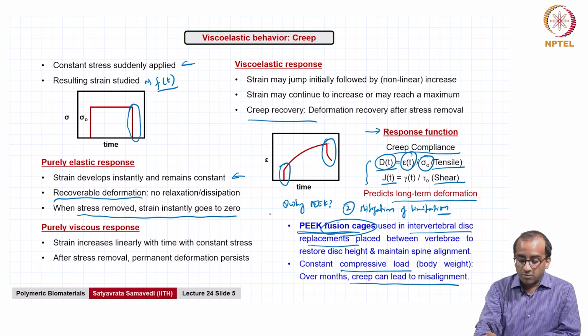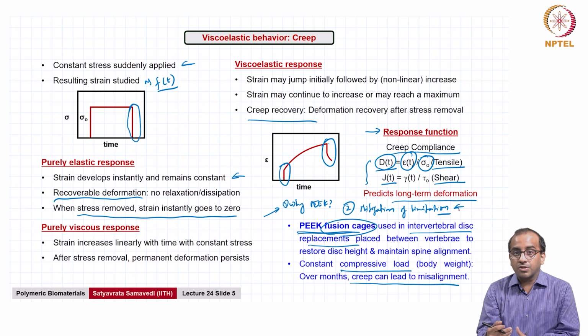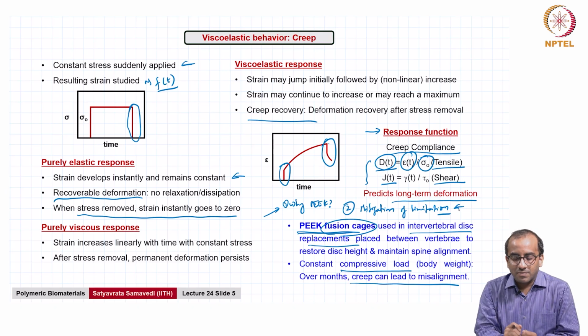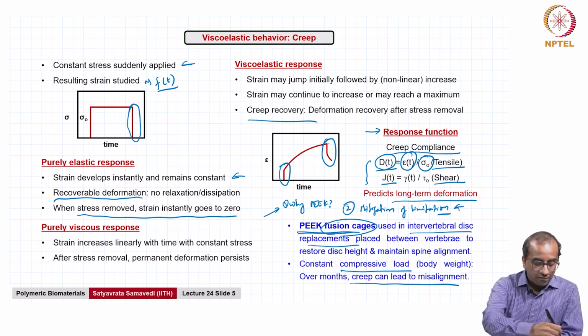The first one is more of a scientific question. The second one is more of an engineering question, because here you are asking from a design perspective, what do I need to do to ensure that creep isn't significant once I have implanted it? So, that is creep. Now, we will move on to stress relaxation, which is the other very important feature of viscoelasticity.